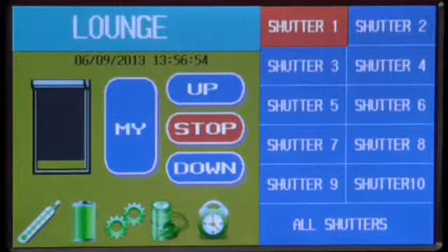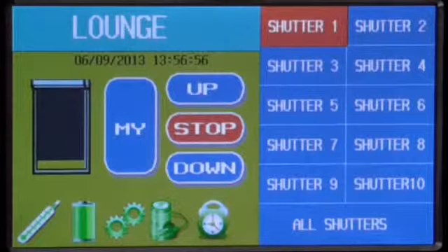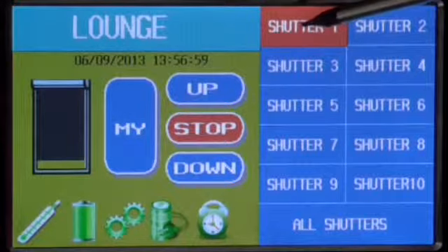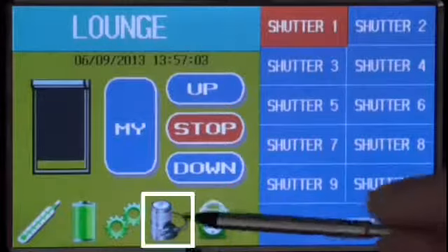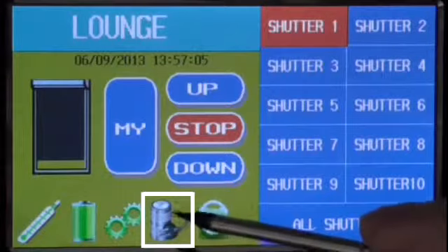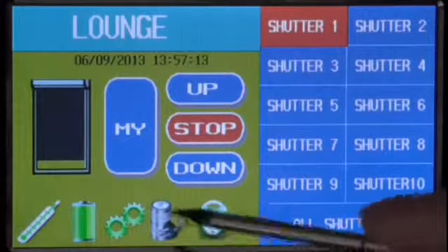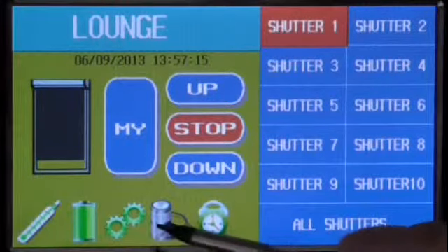Let's pull out a power pack to check how self-diagnosis works. Shall we see how it shows when the power pack is pulled out? Can you see how the power pack previously shown in green is now shown in gray? This means there is no power pack there. Other icons all show the same color for self-diagnosis.